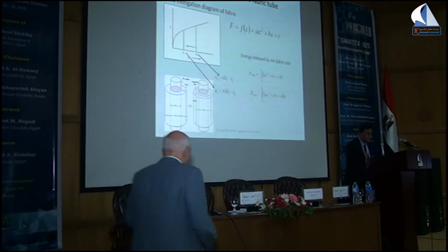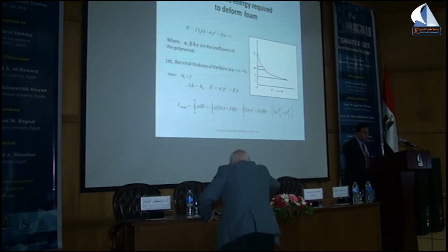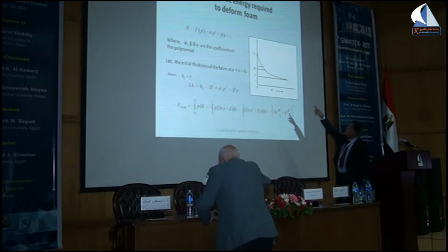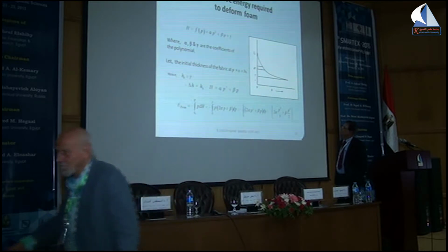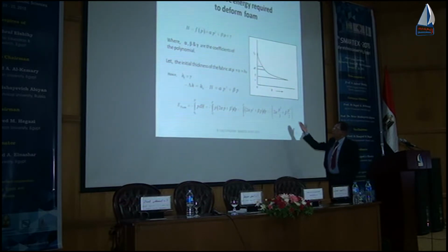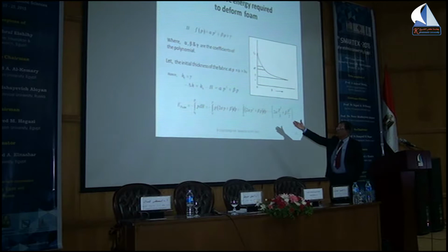So this is what was done. And we could similarly characterize the compressive behavior of the foam by another quadratic equation, and find the energy by integrating this equation.